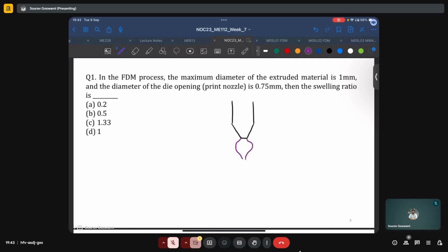We discussed that because of the elastic energy stored within a polymeric material while it is in the molten state, when it is released from the nozzle tip or the orifice, there is a small expansion seen as this elastic energy gets released. The same is not the case for inelastic materials because the amount of energy stored in them is comparatively very small. However, for polymeric materials, we'll see a bulging effect, which is called die swelling.